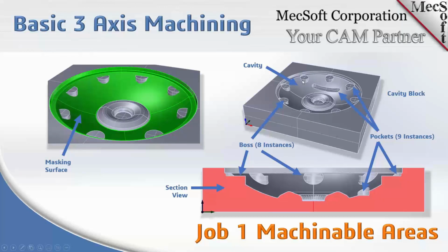And we don't want the tool to roll over these edges. We want to make those edges nice and sharp. So we cut a cross section of the part and revolved it around to create this masking surface, where there's no interruptions other than the bosses sticking out. There's no interruptions in that surface.